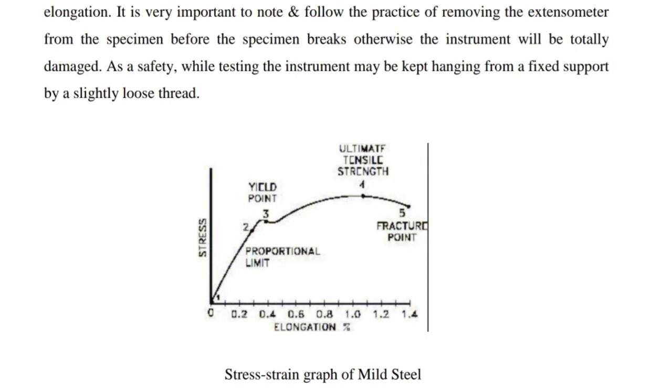It is very important to note and follow the practice of removing the extensometer from the specimen before the specimen breaks, otherwise the instrument will be totally damaged. As a safety measure, while testing, the instrument may be kept hanging from a fixed support by a slightly loose thread.